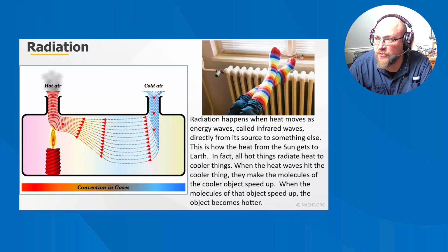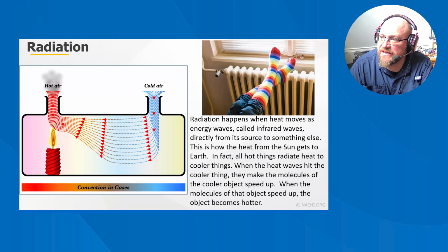You'll feel cool in a room that has a cold floor, walls, and ceiling. The amount of heat lost from your body in that room depends on the relative temperature of the objects in that room. The colder the floor is relative to the temperature of your feet, the greater the heat loss from your body will be as you continue to stand there. If the floor, walls, and ceiling of that room are relatively warmer than your body, then heat will be radiated to your body from those objects or surfaces.